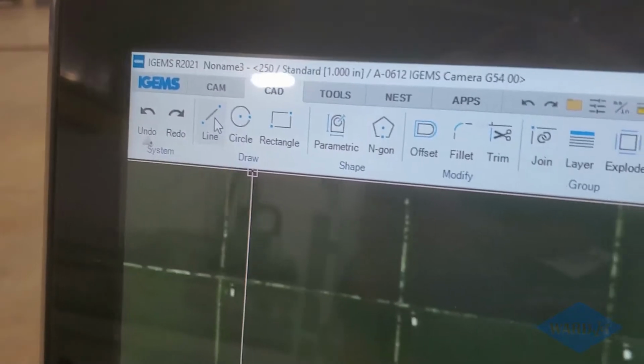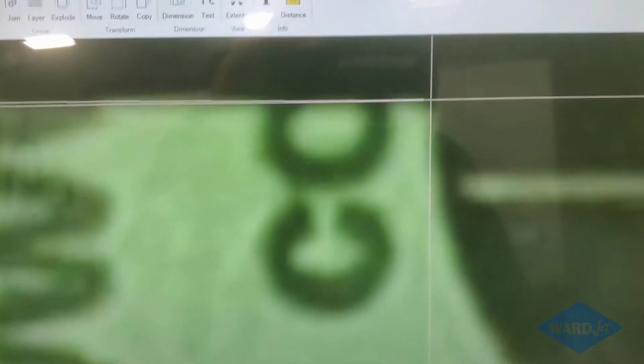then we can do something similar for the outside. So we can draw individual lines. I can use my line command up here, and I'll start up at this corner, and we'll come over to this corner, and I guess we'll stop about there. And I'll just do all my lines first, and then I'll come back and do the arcs.